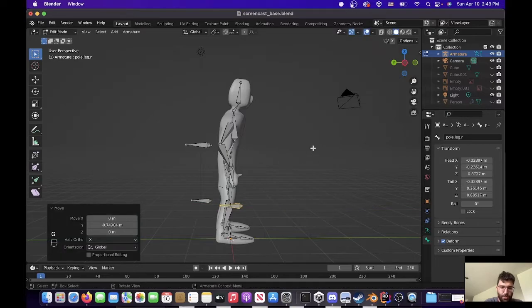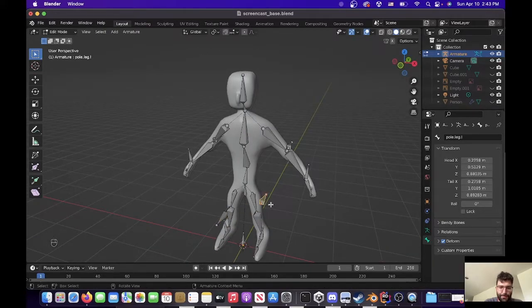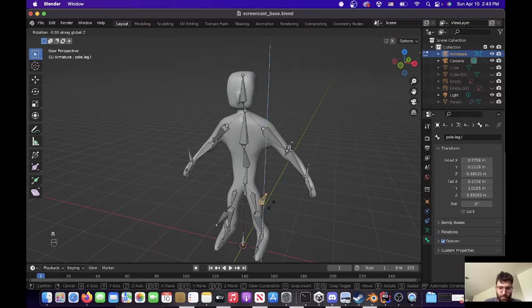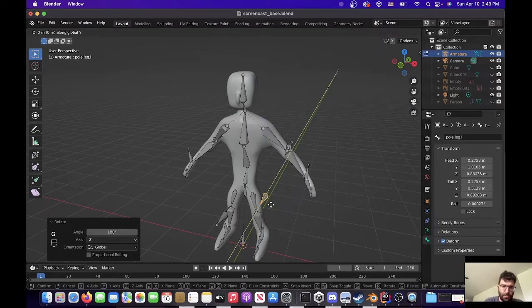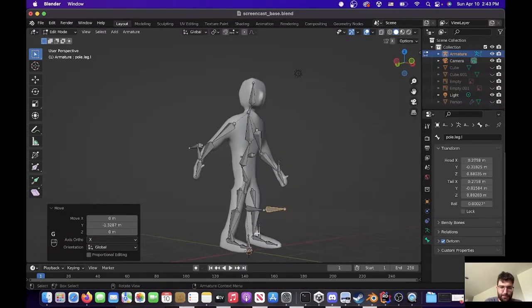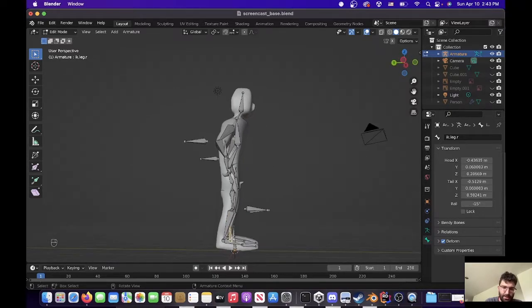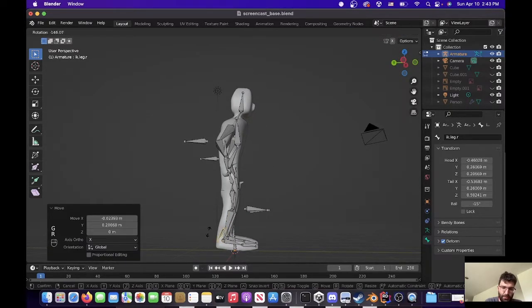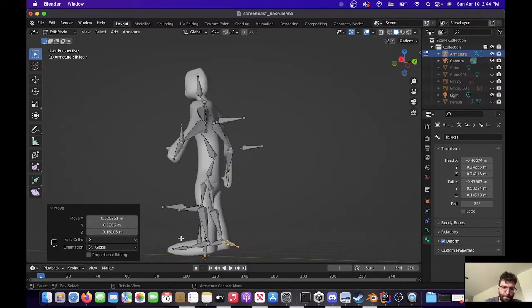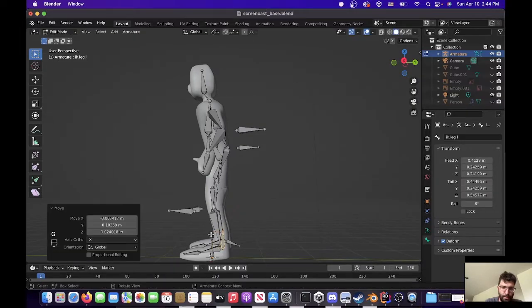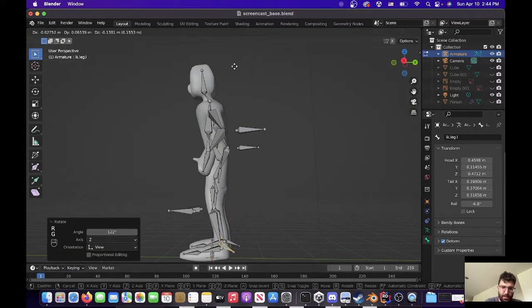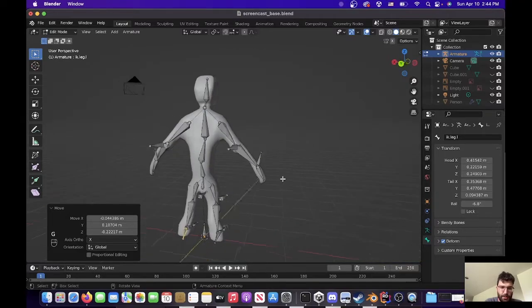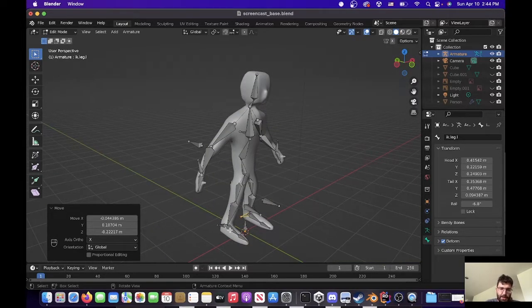And then we actually want it, the pole should be, your knees point, so the pole should point in the direction of the joint, basically. There we go, like that. And then these guys should align fairly closely with the heel, like that. And now we're ready to do IK targeting again.